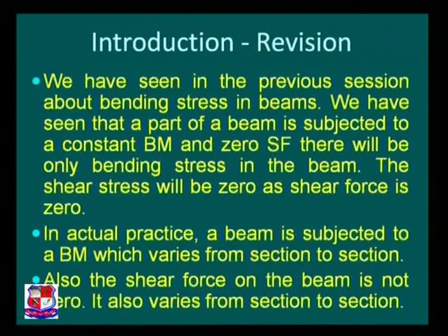Now let us revise what we had studied up till now in the chapter on shear stress. We have seen in the previous session about bending stress in beams. We have seen that a part of a beam which is subjected to a constant bending moment and zero shear force will have only bending stress. The shear stress will be zero as shear force is zero, which is not possible in an actual situation, because a beam subjected to any kind of loading is subjected to the bending moment as well as shear forces, which change from section to section.